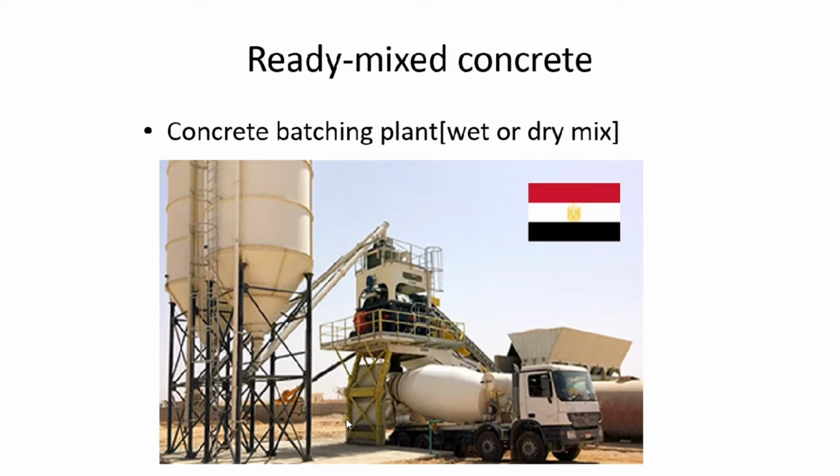And then let's talk about ready mixed concrete. Ready mixed concrete always comes from a batching plant where you've got silos of cement, extender or fly ash, which is dispatched into a drum where it gets mixed together with the material from the bins of sand and different types of stones, transported into that container by means of conveyor belts.